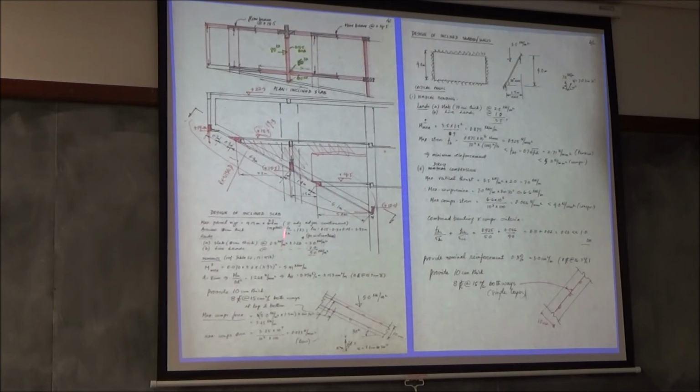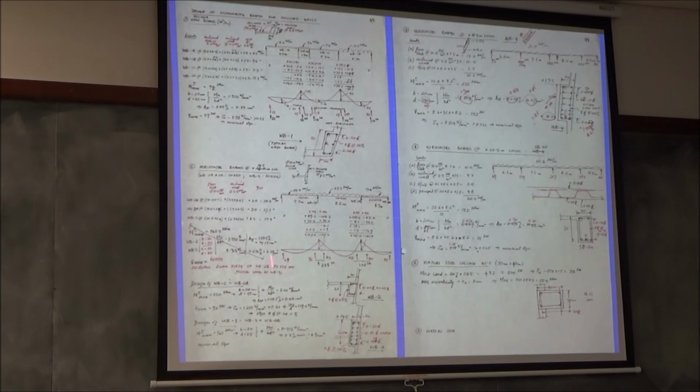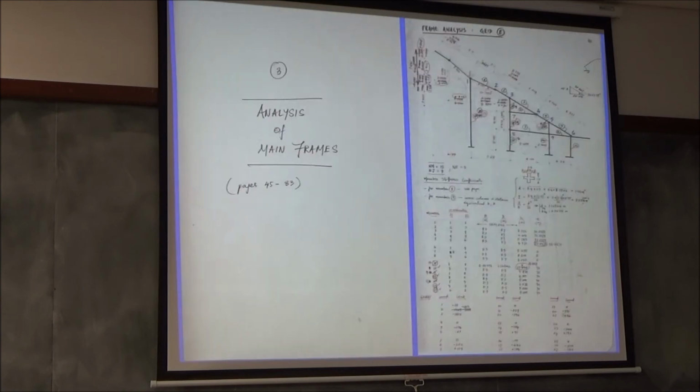So lots of calculations. There are a lot of inclined slabs and walls, so you make some suitable assumption and do it. Typical bending moment diagram, shear force distribution, you should know more or less the design for the different elements. Some are inclined, some are vertical.